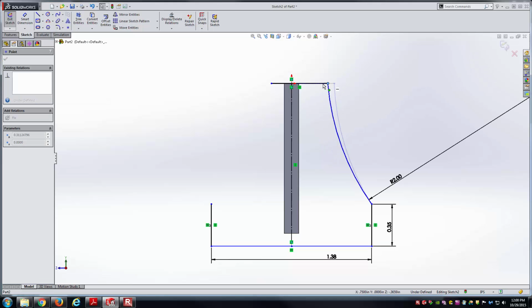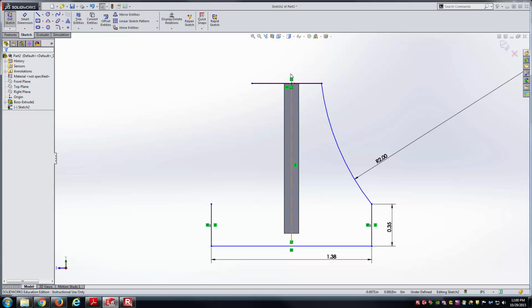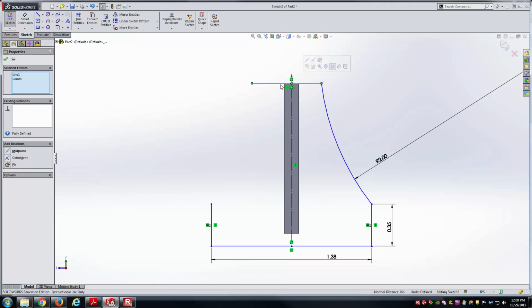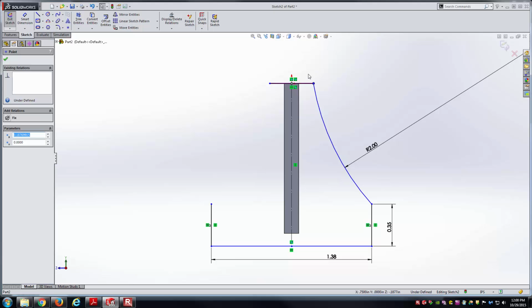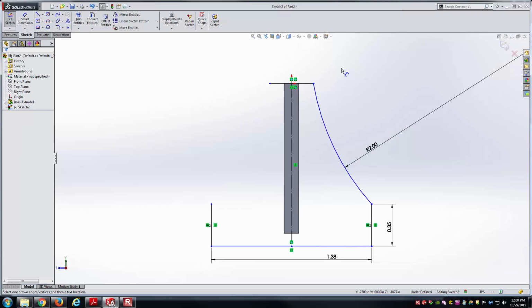You can see here on the top hand side I'm kind of inspecting to see what it does as I try to manipulate things, and I don't have it as the midpoint. You can see these geometric relations are coincidence and a horizontal here, and so I'm going to go ahead and hold control down so I can select both the line and the origin and make sure I apply a midpoint relationship here. And then also I believe on the drawing I have some width dimension here at the top to define the length of that line, and it says right here in the right view 0.5.